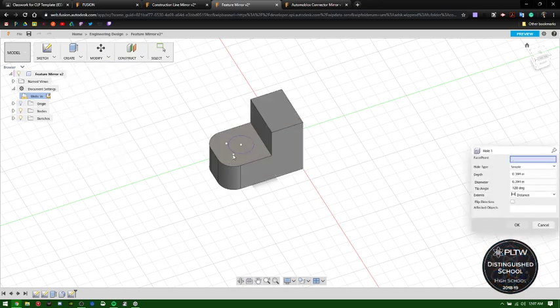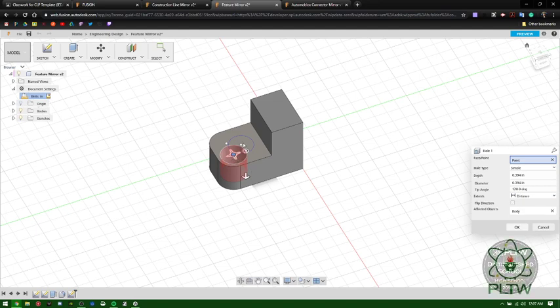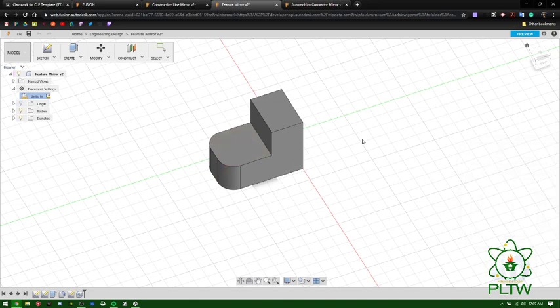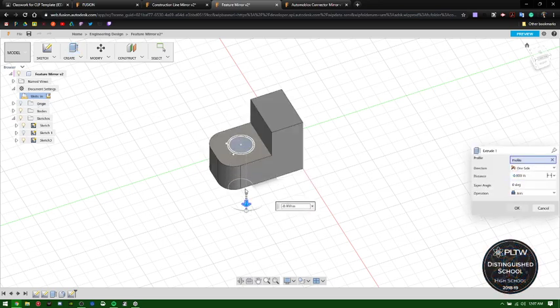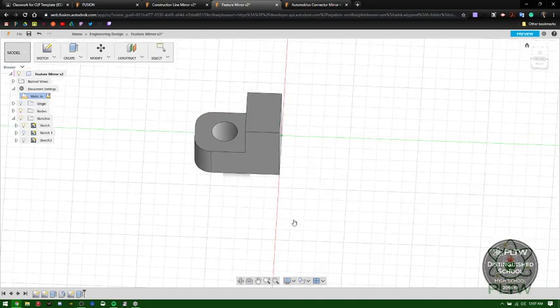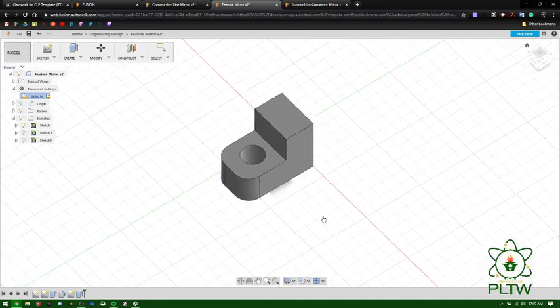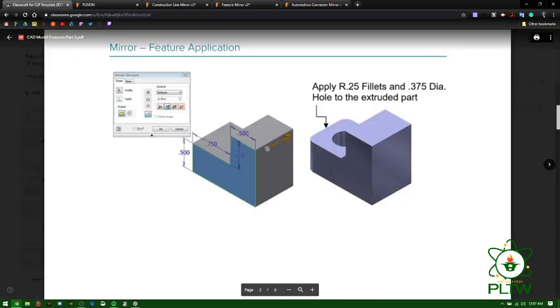And basically, you can select whatever face you want, and then you can move it around, make it the thing, all that kind of stuff. Or you can make it easier on yourself and just come over here and turn those sketches on, which they're on. Extrude, take that, drag it down, and instead it automatically changes the cut. Press OK, and now you got your hole that goes all the way through. That's the easier way. Okay, hopefully that fixes that piece.